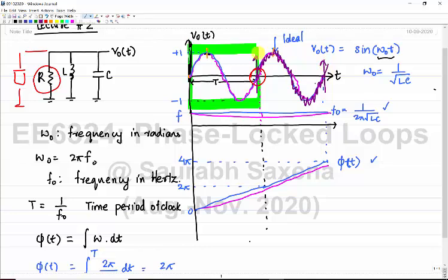because my events, my rising zero crossing going from negative to positive is fixed, and which marks an event in the system, and I am going to synchronize my data rate or other things, or even the sequential logic with the rising edge, or zero crossing. So it may have more zigzag, which is like you are having a lot of voltage variation, but till the time you keep this fixed, it's fine, because your event remains fixed.